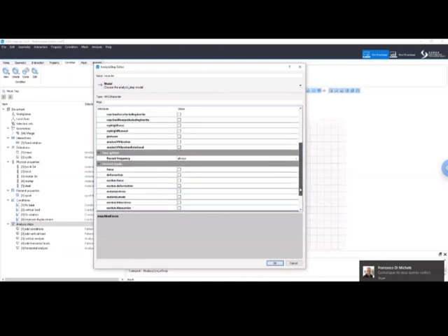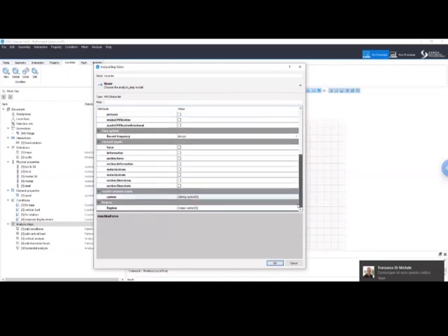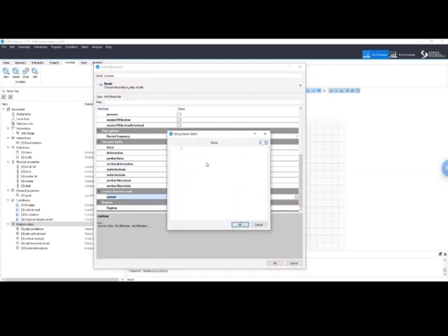And then I want to record something on the elements. For example, I would like to record the stresses and strain at every integration point. But I also want to record something else. My material model here, the damage TC3D, has some other output variables which are not listed here. So whenever you want to record some variables which are not available under the default ones like stress, strain, force, and deformation, you can always do it here. So my variable is actually damage. The damage is the tensile and compressive damage. So you can use the custom command.